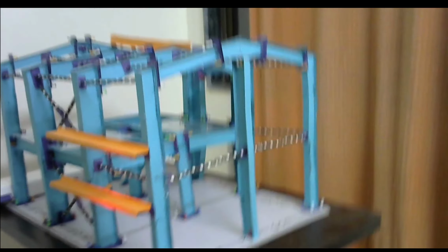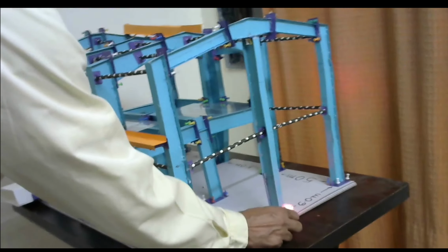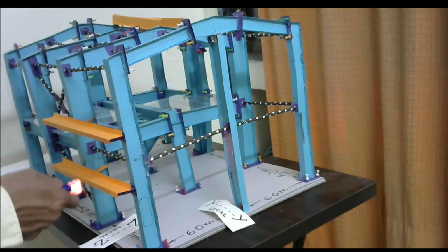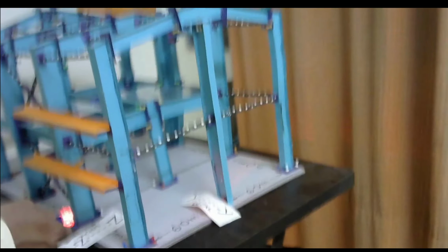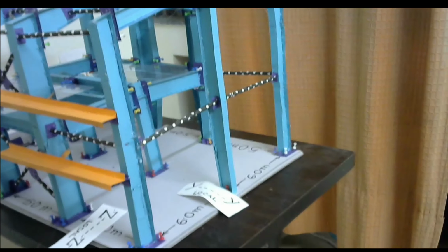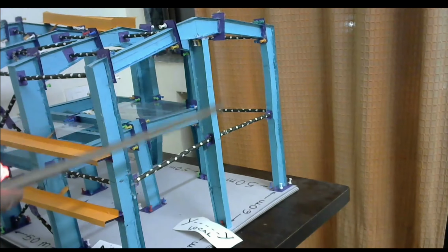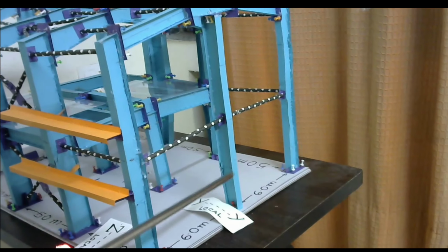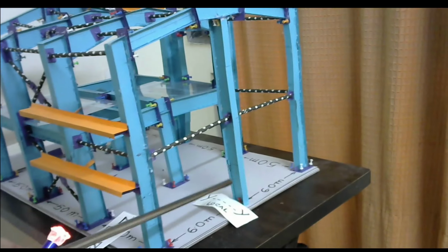Then LY. This is our local LY axis. So now for LY axis, this is about local LY. This is the gravity column. So restraints are being provided by this portal frame. This is now acting as a portal frame. This column is providing lateral restraint to this column. So LY will become 1L. So this is 1L again. So 3 meter.